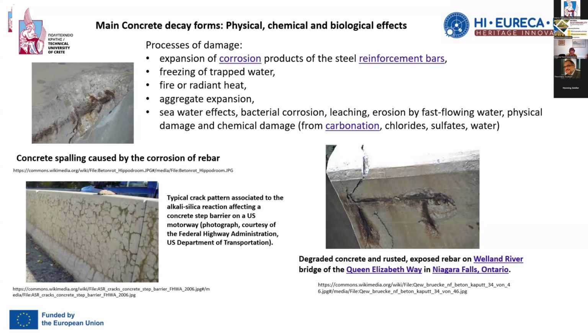We have an expansion of corrosion products because of the steel reinforcement bars that are found in the concrete, and especially in reinforced concrete. Then we have problems with the freezing of trapped water that creates stress, and therefore a lot of fissures were developed.